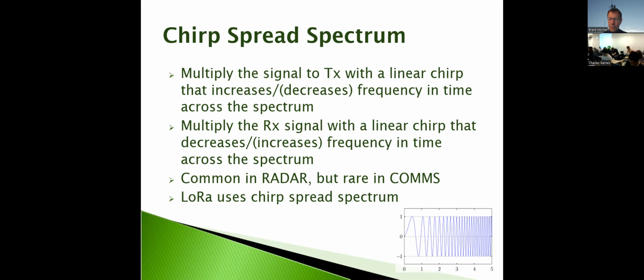And so you take your signal coming in and you multiply it by this chirp, and now the composite signal that you transmit will be constantly changing frequency throughout the duration of this chirp. And then generally it's set back down to the low frequency and repeated.